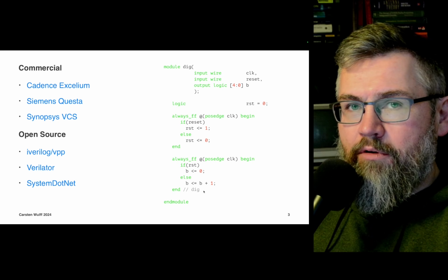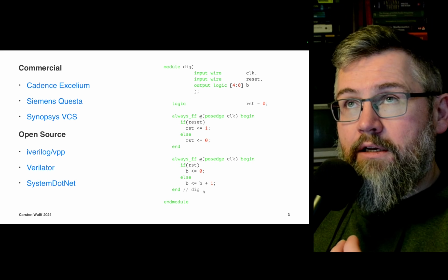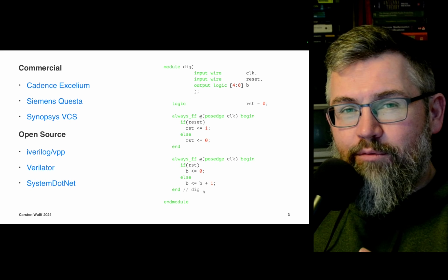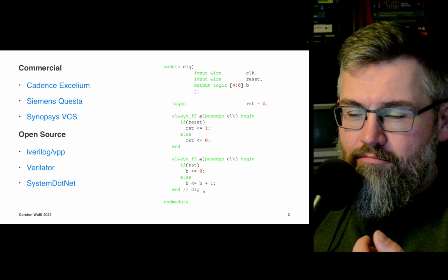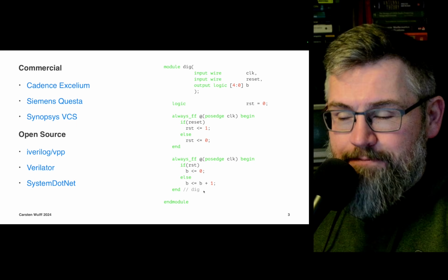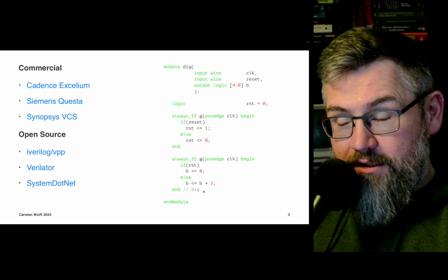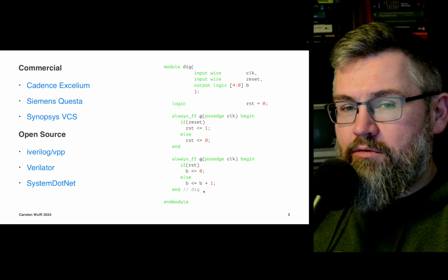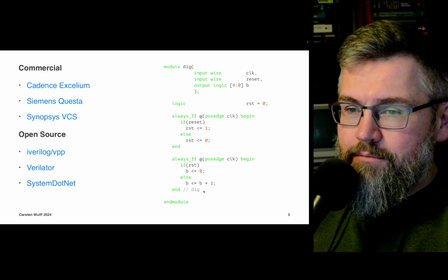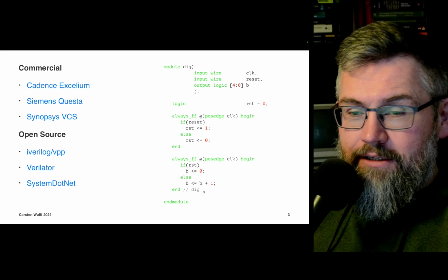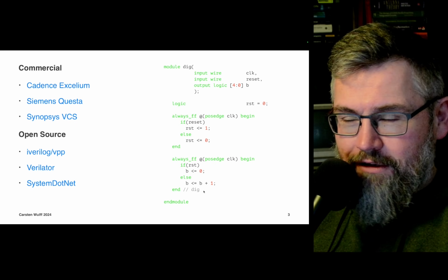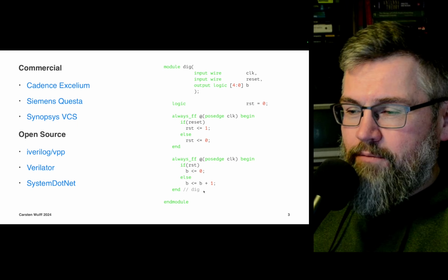In these types of SystemVerilog languages, it is comfortable and gives a warm fuzzy feeling to write these kinds of functions. It's easy. In analog simulation, making a counter like what I'm showing you right now that runs fast, in pure spice with sources and voltage-controlled sources and things like that, is actually quite hard.